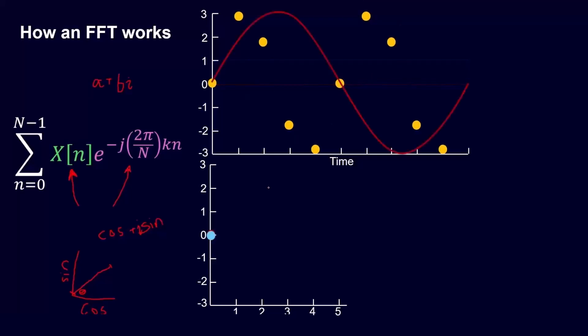Now let's do a 1 hertz sine wave. You could see right now that if I were to multiply this point here by this point here, here by here, and sum the result together, these don't really look like they would correlate. And if I sum them together, I'm going to see that I get 0. I could do it again for a cosine wave, and I could really quickly eyeball that the cosine wave doesn't correlate either.